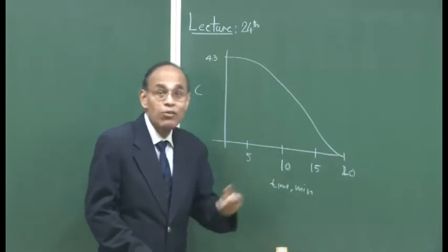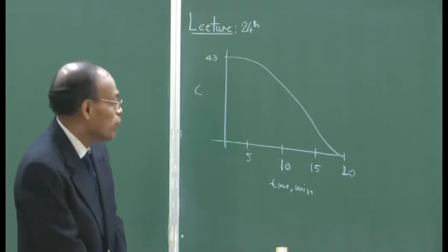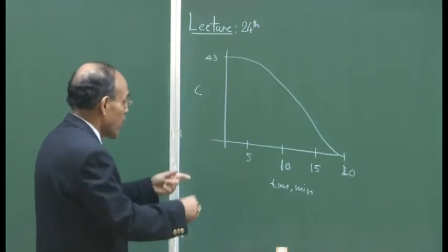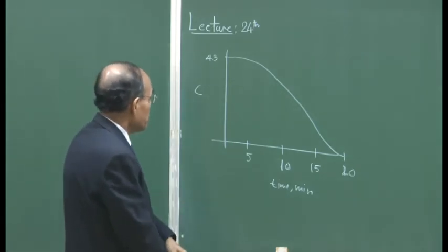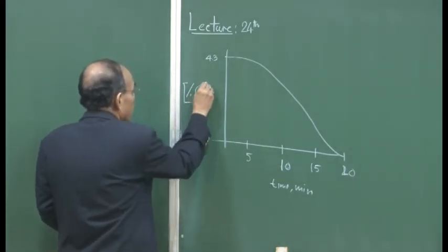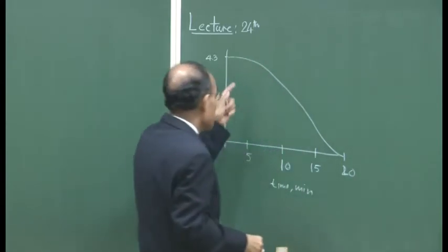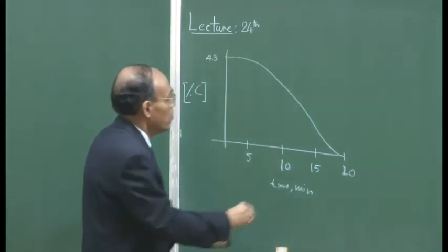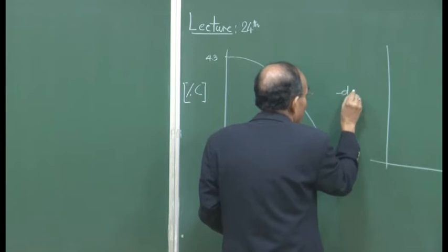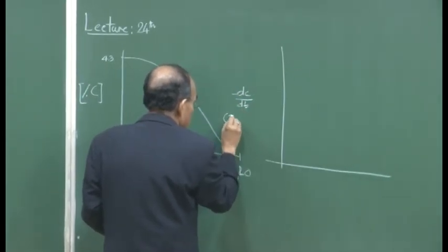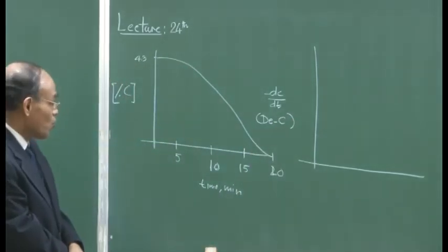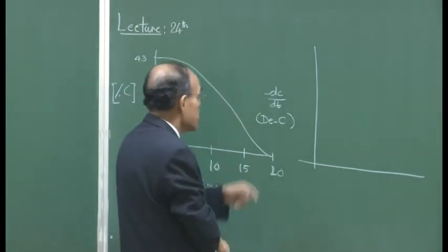You must understand the steel will contain some carbon depending on the grade that we manufacture, and that could be your target chemistry. So, this is weight percent C in the metal, and accordingly if I translate this figure into a plot of decarburization rate, which is minus dC over dt. This is just like our notation: desulfurization, dephosphorization I told you, DEP, DES, and this is decarburization.